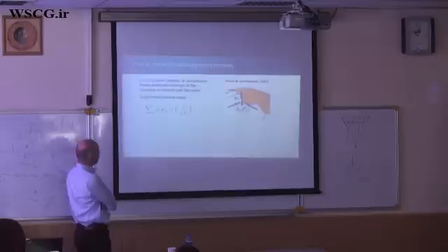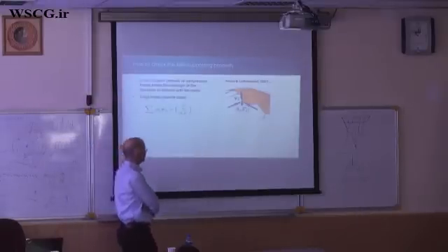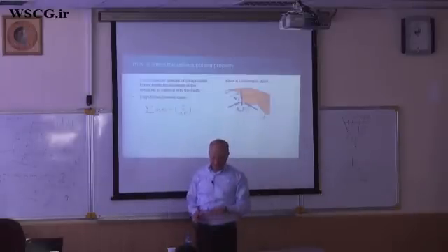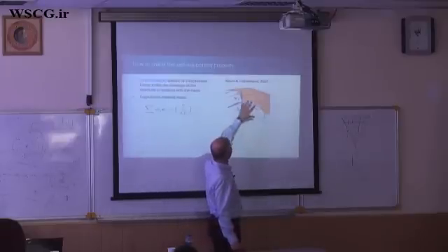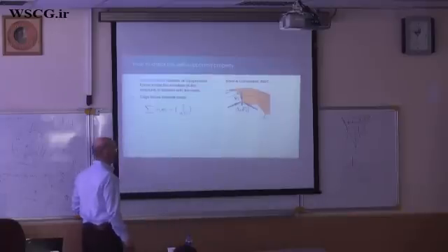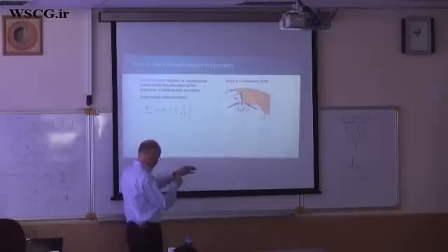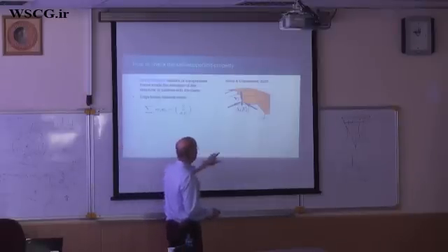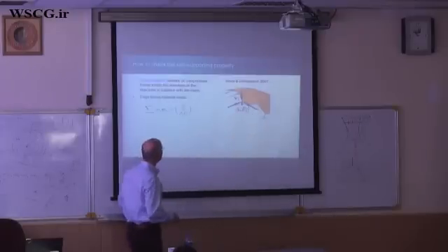And mathematically, how do we express it? Let me repeat. I had it in my first lecture. A structure is self-supporting if I can put a network of forces, a mesh of forces, inside the hull. So it must be within these bricks in the previous case. And along each edge you have acting forces. They have to be compressive.